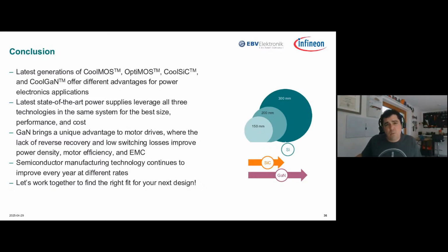You can see this in these figures here in terms of the wafer sizes. We're producing silicon power transistors primarily on 12-inch 300 millimeter wafers. Silicon carbide is gradually transferring over in the industry from 6-inch to 8-inch wafers. Meanwhile, GaN is mostly on 8-inch already, and it's moving towards 12-inch because it's produced on silicon, so we can take advantage of those readily available 12-inch silicon wafers. So alongside these larger wafer sizes, we're seeing advancements in the figures of merit and cost positions.